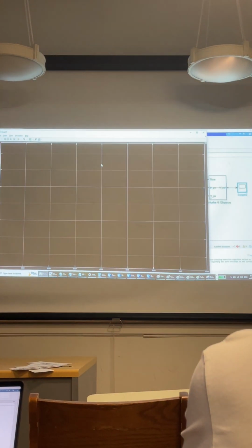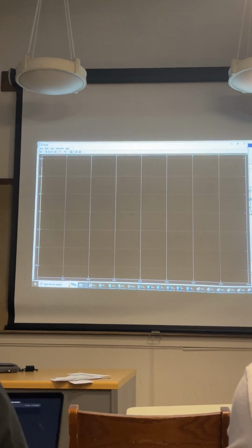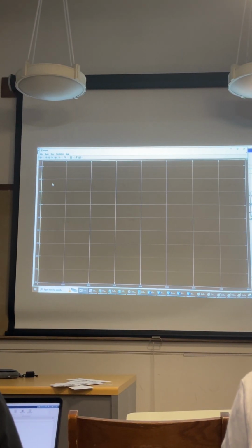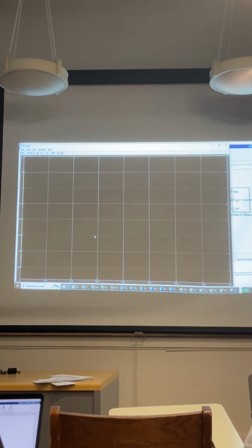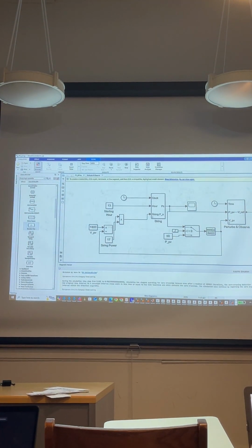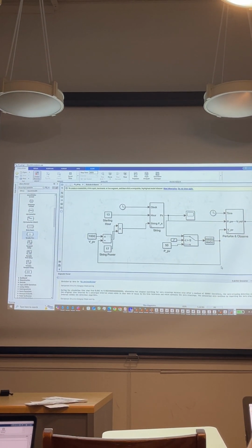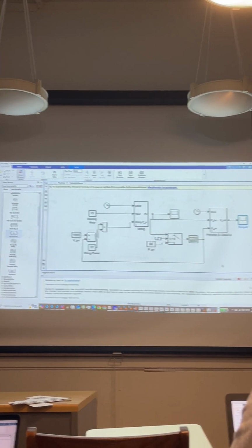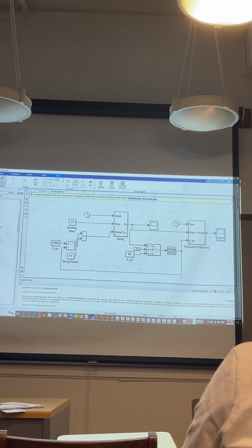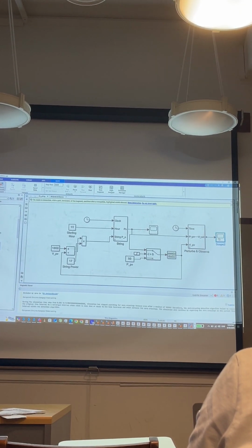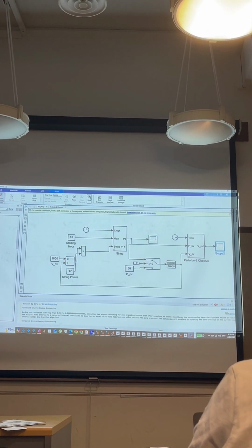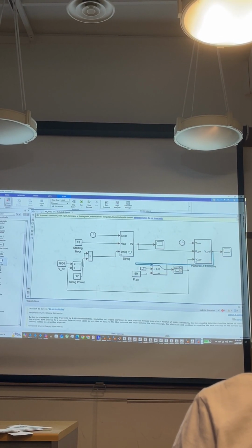Let's see how the power looks. Okay. The voltage is slowly increasing. Okay. What's the time here? Let's see. 30 seconds, it's going to run faster in a bit. I forgot to check if it is the ode23t. Is it? Can I see it? No, it's ode45. So let's change that because it's going to run slow and also cannot see much.